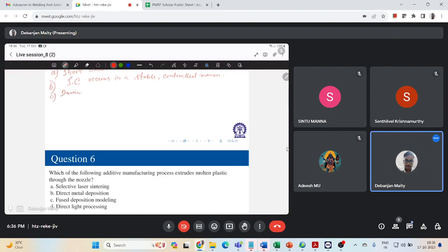Then during the metal transfer, as your droplet is detaching, the current drops to near zero, and thereby any spatter generation is avoided.